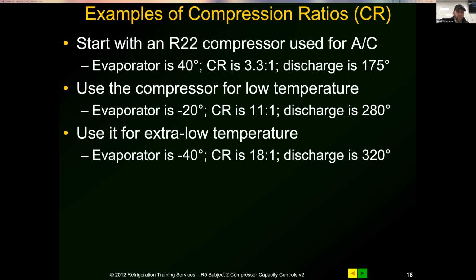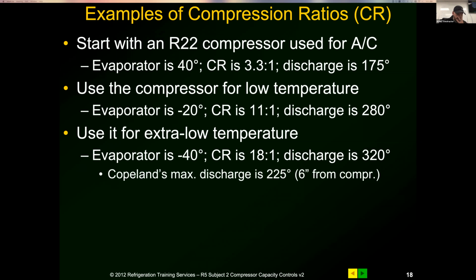So we go out, we change it, we throw a new compressor in, and nobody checks compression ratios. I would dare say that probably only 10% of the techs out there check their compression ratio on a startup. It's a big deal. Manufacturers want to see it in that 3 to 6 range.